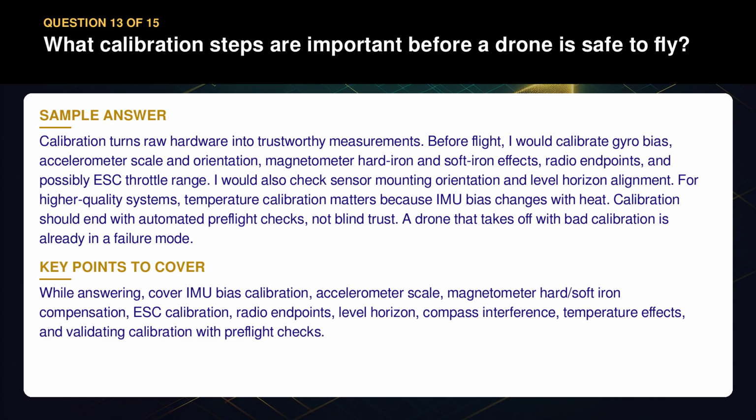While answering, cover IMU bias calibration, accelerometer scale, magnetometer hard/soft iron compensation, ESC calibration, radio endpoints, level horizon, compass interference, temperature effects, and validating calibration with pre-flight checks.